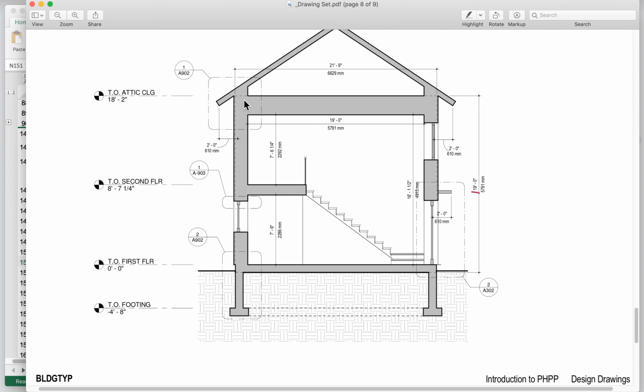So how is this detail effectuated? How is the building built at this point, and how is it going to affect our thermal performance? So I would say that we've got three thermal bridges that we want to capture for our building here. We've got our floor or our footing detail, we've got our eave detail, and we've got our wall outside corner detail.